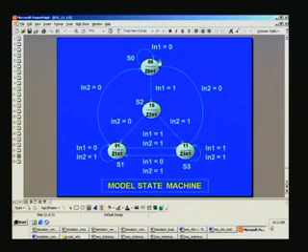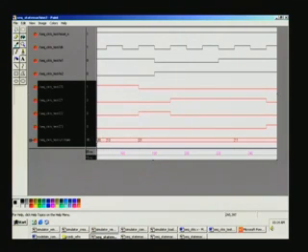So the next one is, so long as in1 is 0, it continues to be in the S0 state. In fact, that is what you have already seen, and from this it can go to the next state provided in1 is 1, that is, it goes to the S2 state. You can see here this is S0, and it is going to the S2 state here, and in S2 state, although it enters the state right at this positive edge of the clock, the actual lamp output will go only at the next positive edge of the clock right here.